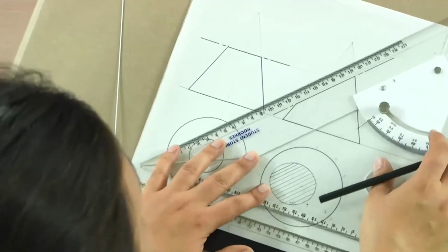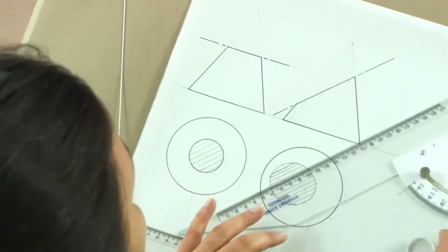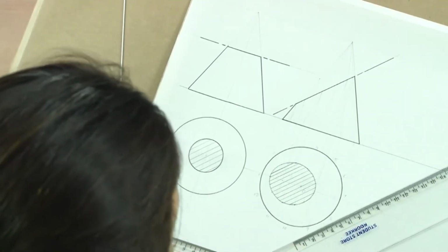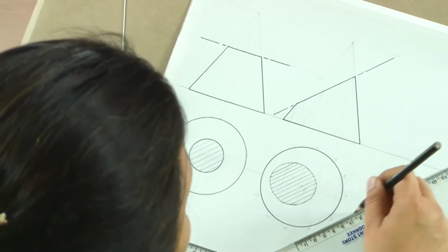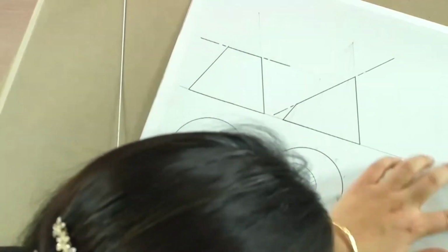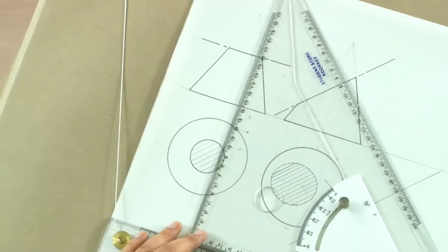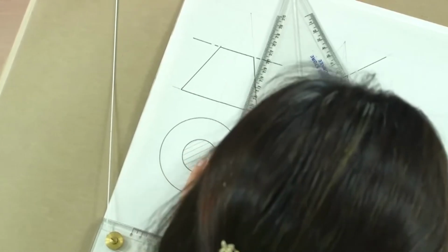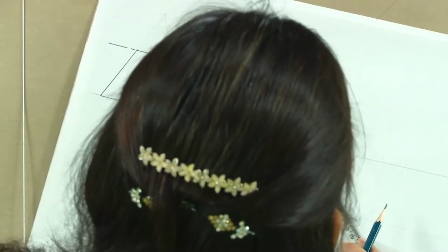So we can draw an auxiliary plane which is parallel to the section plane, which I have taken this side because there is no space. However, you could take it wherever it is convenient. The only thing is it has to be parallel, and all we are going to do is bring back the projectors for the generators. So all I am doing is bringing back the projectors of the generators here.